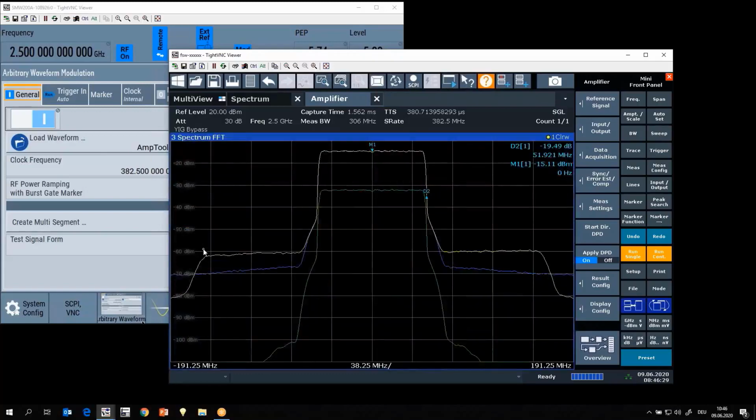If you look at the spectrum plot here, on the right-hand side we can see that the, let's call it shoulder, is pretty flat, where we have a slight slope on the left-hand side. What does that mean? Basically, if the shoulders are flat, it means it's more or less noise that we're looking at. And as long as we still see a slope here, it basically means there is still some non-linearity, intermodulation, causing the shape of the shoulders.